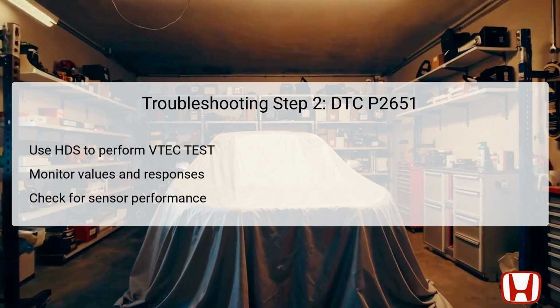In the second troubleshooting step, utilize the Honda Diagnostic System, HDS, to conduct a VTEC test. This test assesses the operational status of the VTEC system by checking various electronic parameters and sensor outputs. Monitoring values from the rocker arm oil pressure sensor during this phase is essential, as it helps determine if the sensor is responding correctly to changes in oil pressure.